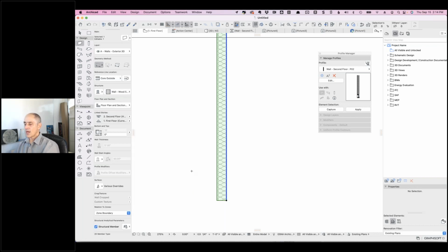So what you do is you have one wall here, you have another wall you draw on the outside there that is the cladding that's going to be removed, and another one that's the cladding that's going to be added. And then those cladding walls have demo and new attributes, whereas this is existing to remain. And when you put in a window or a door, you'll have to punch out extra holes in the cladding because you won't automatically get them. So it's a pain.